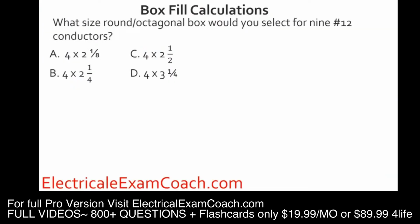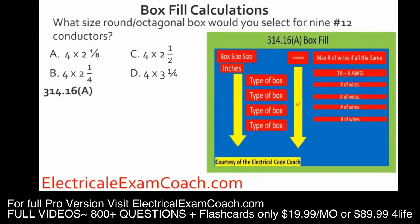What size round octagonal box would you select for 9 number 12 conductors? For this one, we're going to be using table 314.16a. We're going to start here and we're going to find our gauge of wire. Then we're going to come down and we're going to find a box, making sure to cross over and double check that we don't crest over into a different style box. We want to stay in the round octagonal. We find our conductors, we find the one that fits it, we slide over and double check ourselves, and we're going to select A. Great job!